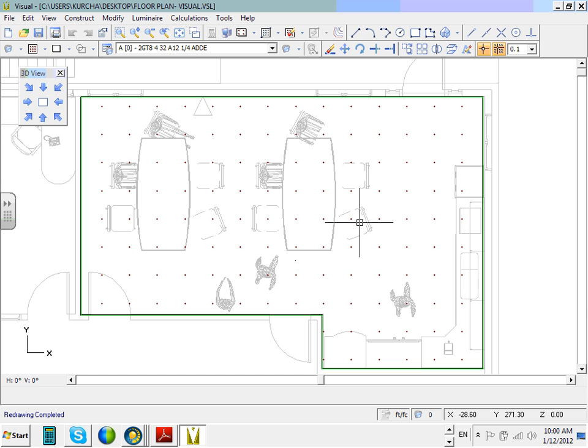How do you place the fixtures? We haven't done the lighting calculation yet, guys. Here's what you do when you place your fixture. This is a 2x4 fixture like this, right? Exactly like this one. When you place your fixture, you're going to orient them. Technically, the longer side goes to the longer wall. Not a rule of thumb, not really science. And if you look at this one, this will give you a hint.